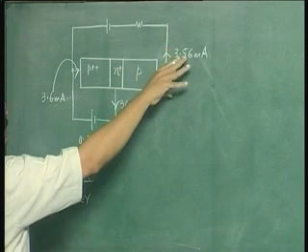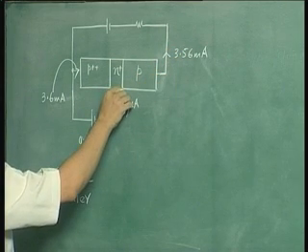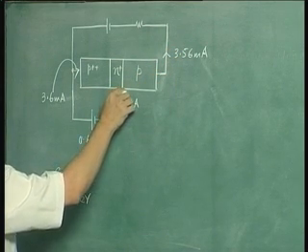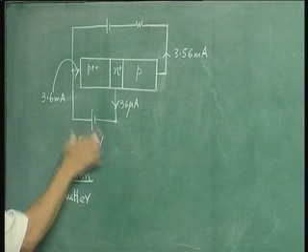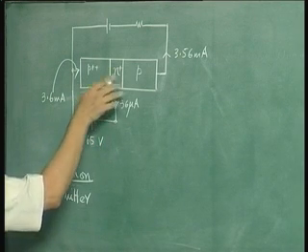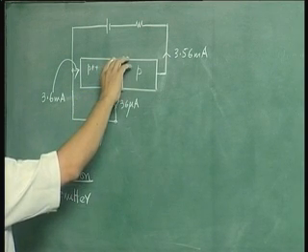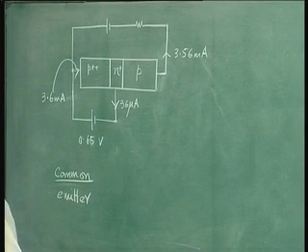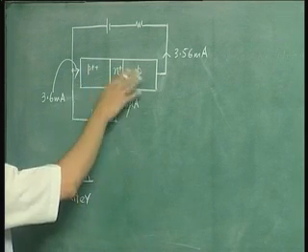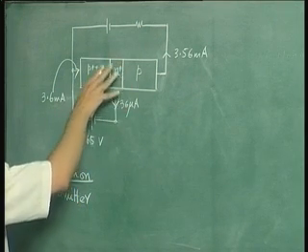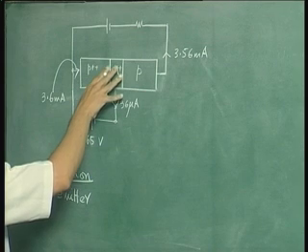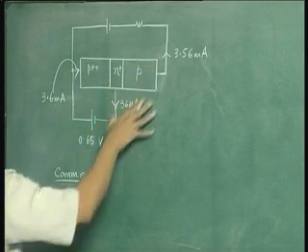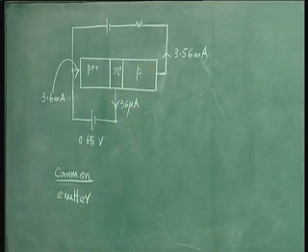So long as you don't get into the effect of IC naught and you maintain zero or reverse bias across the collector base junction, if you maintain 0.65 volts across the emitter base junction and your device has an emitter area of 100 microns by 100 microns, then for the other doping and lifetime and diffusion coefficient conditions, you are going to have the same currents flowing in the device.